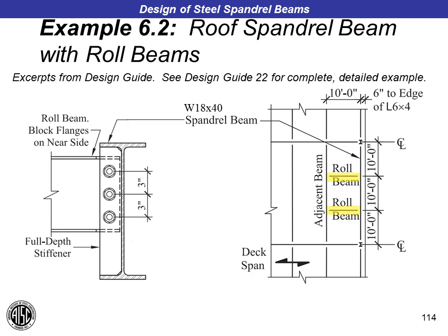Right, that's a good question. Typically, no. We usually provide a double angle connection or a simple shear connection to the adjacent interior beam that isn't intended to restrain or provide a rotation to the interior beam. So all we're doing is providing a vertical shear reaction upward at the adjacent beam.